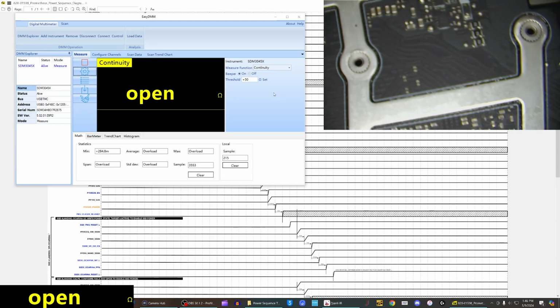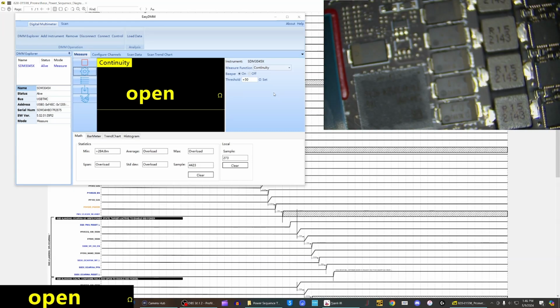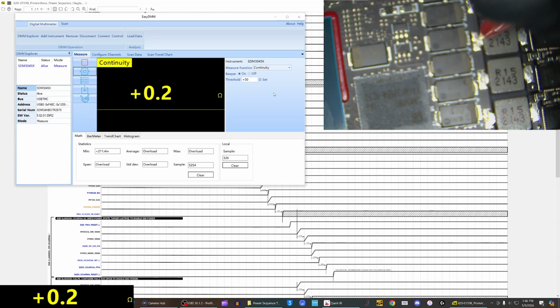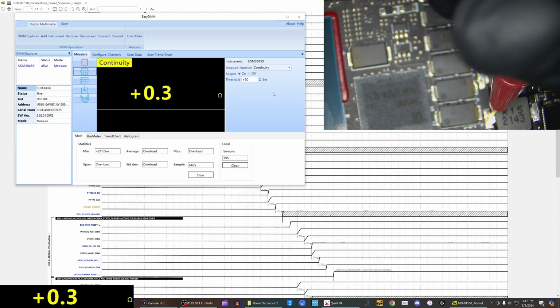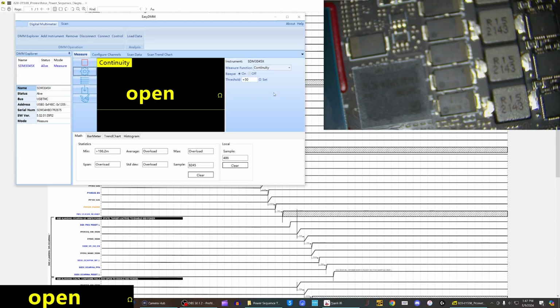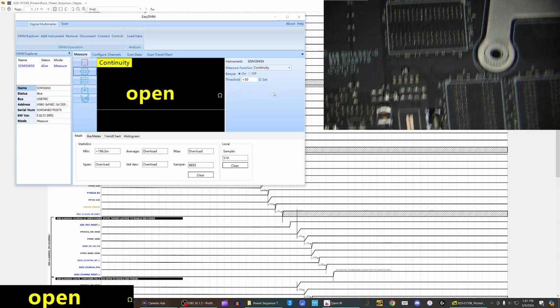One other thing, this is a 6000 series Ryzen board. These lines all look like they have a high side MOSFET short. The natural resistance on these coils is probably supposed to be like 0.2, 0.3, 0.4. I've seen a lot of those ROG Zephyrus machines, and they all measure like this even when they're working. So I wonder if the Ryzen chips seem to survive the high side shorts more. This doesn't have that, I don't think. We'll see. Okay, in any case, I'm going to desolder this fuse.